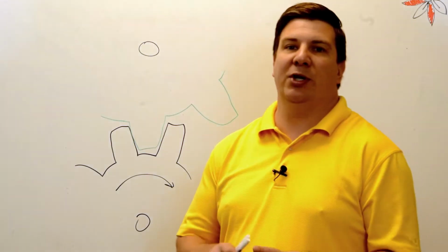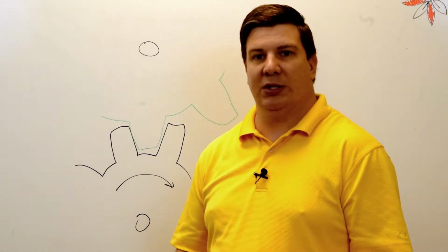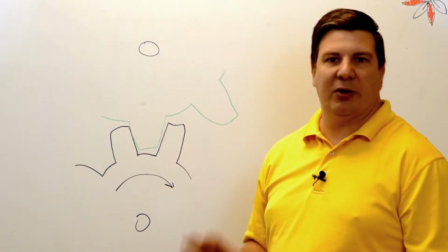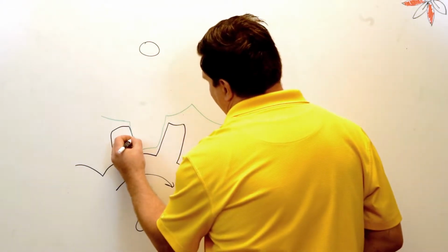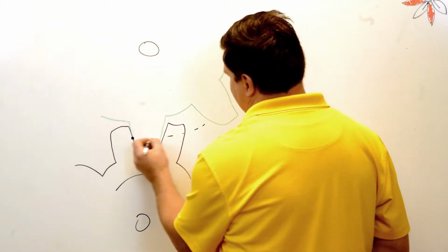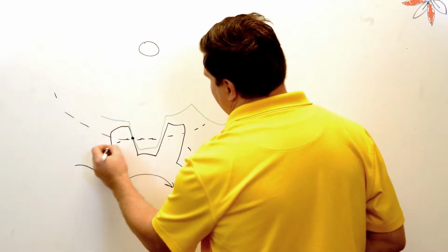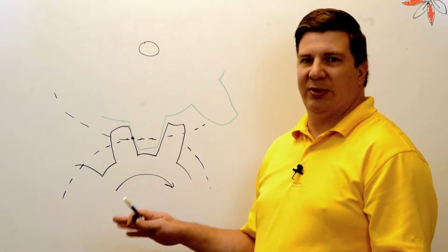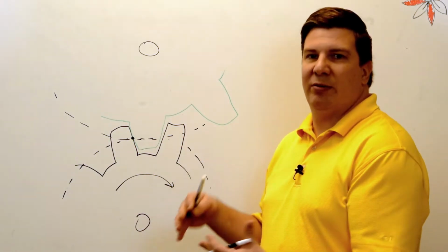So we're now moving on with our gear study here, and we're going to talk about the transmission of torque and force. All right, so the first thing we're going to do is some free body diagram on our gears. Okay, so right here we have a point of contact, and we're going to assume that it's just about at the center line of the pitch circle. All right, so right where those two tangent points. Now it's not quite there, but we're just going to assume for this analysis that it is, because of the involute design. No matter where it contacts, it will have the same effect.